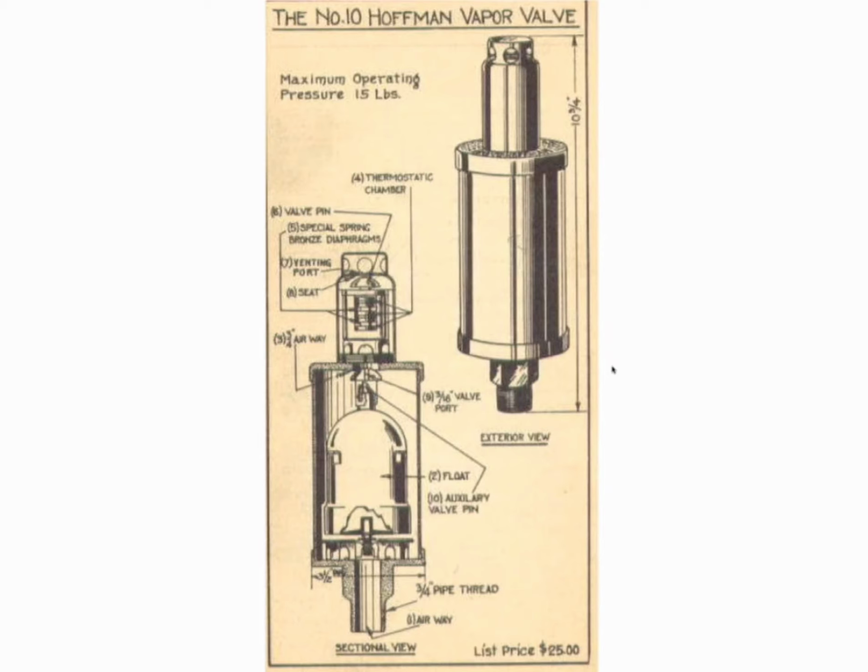So if you're going to go with a large vent for a steam system, for a main or a return, I would say stick with a Gordon's. Go with a Gordon's number 1. Or even if you feel that's not enough, if you've got a 3/4 inch opening, maybe make a small manifold and put 2 of them on there.